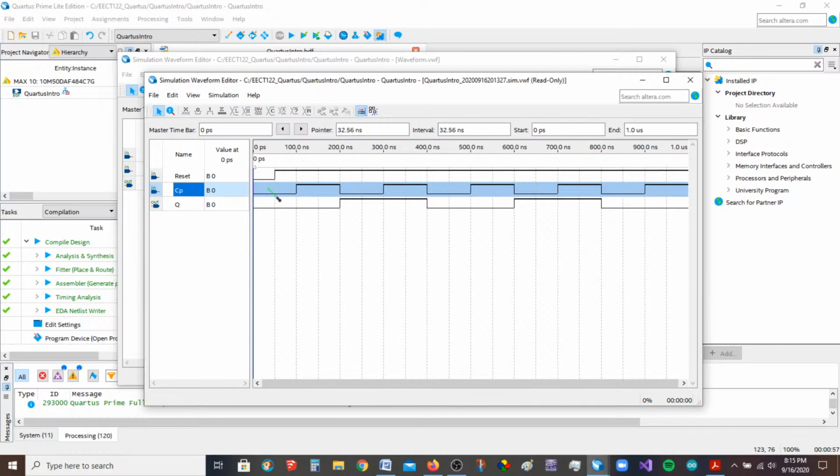Otherwise, you'd actually have to attach some actual clock pulse to the inputs. Which, if you have something that can do that, if you have a function generator, you could do it. Make sure it's at TTL levels though. If it's too high, you'll burn out the input and damage the board.